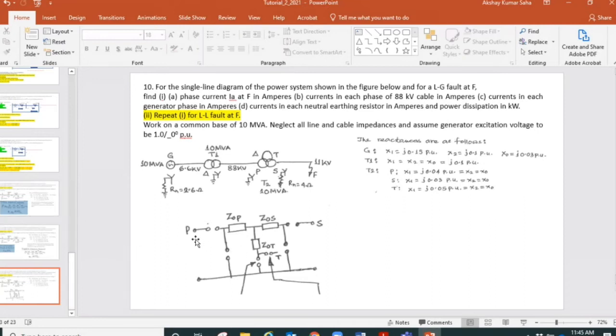We look at the general part first. This switch that you see here is going to be closed, because that tertiary winding is connected in delta. I have not shown this closed yet. I will show you the closed one in the original zero sequence one when it is going to be copied and pasted. So this is in delta, it will be closed, and this link is in between.